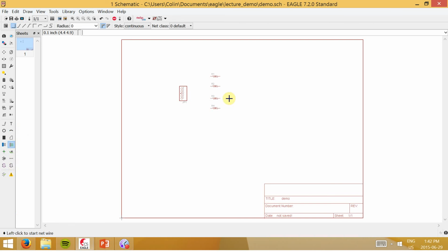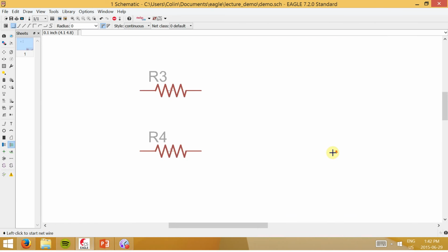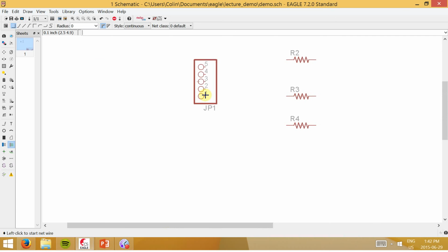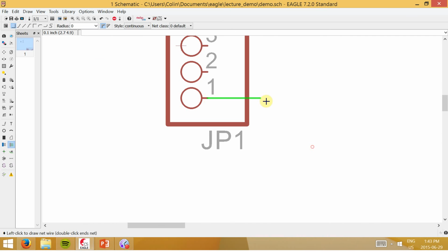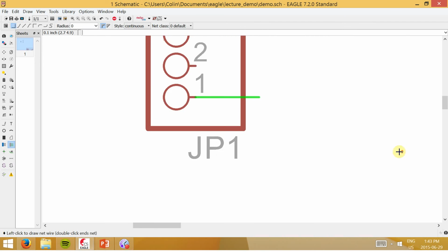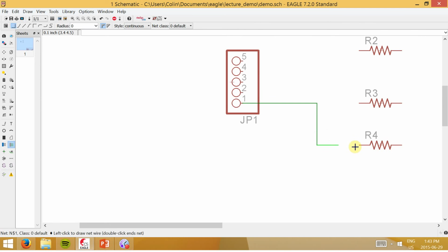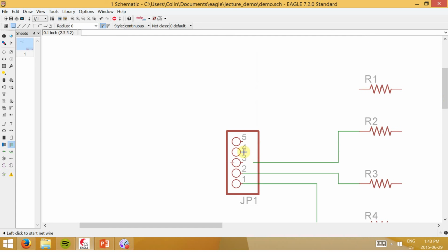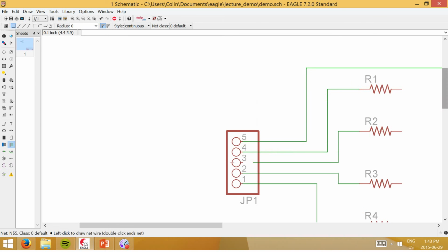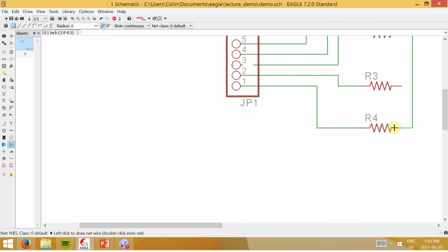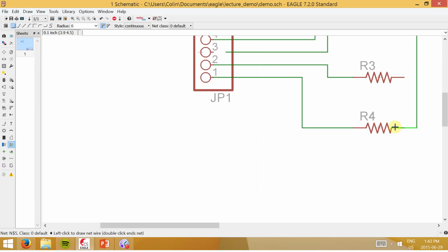So I'll draw an electrical connection, and you can zoom in with the scroll wheel. And because I'm using the net tool, you want to make sure you click on what's the actual pin. So here I clicked on that one point, and we'll check afterwards that we have everything connected. If I miss, for example, that one did not hit the pin, we'll be able to detect that afterwards. And there's sort of 2 ways to do that. The other thing you can do is if you go too far, it also won't make an electrical connection. So if I drop it there,